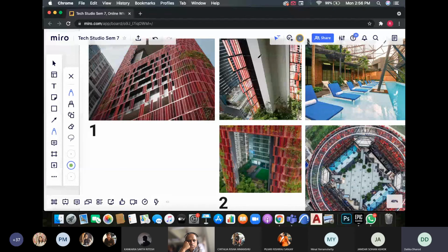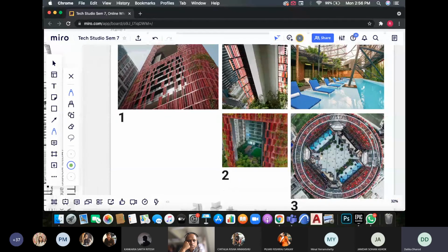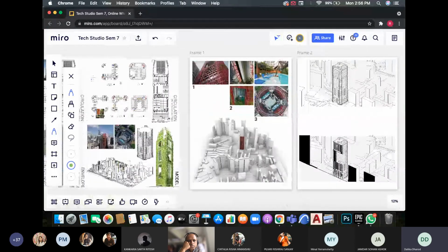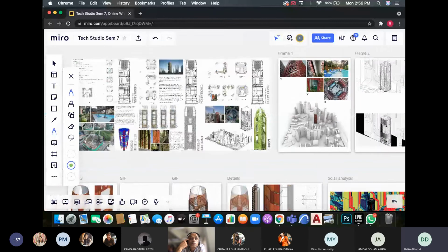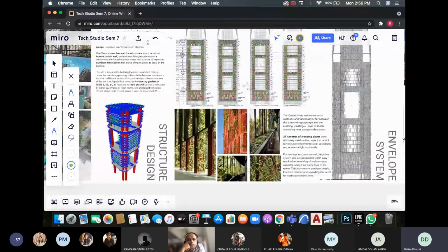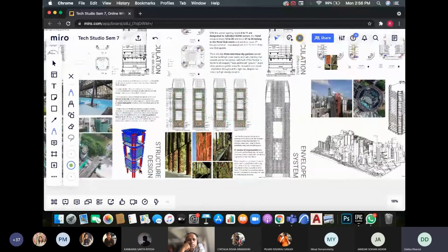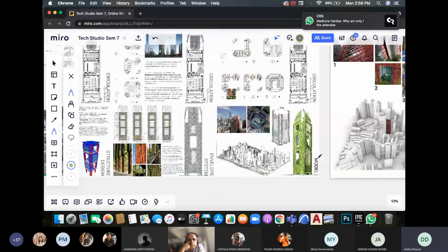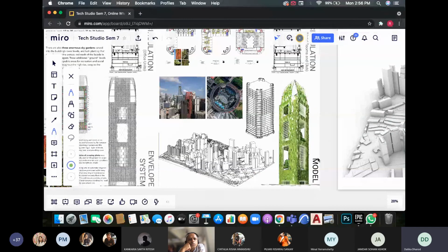So we were not understanding how the seismic forces would act in this building, in the concrete core basically, because the skin, we believe, is independent of the seismic forces, but we're not understanding the inside bit of it, how the forces would act over there. No, it's a straightforward plan. First of all, let's look at the qualifying lines, right? One is it is a symmetrical plan, correct? It has a central core stiffness, as well as the corners are also stiffened because these corners are also designed as cores, correct? Yes.